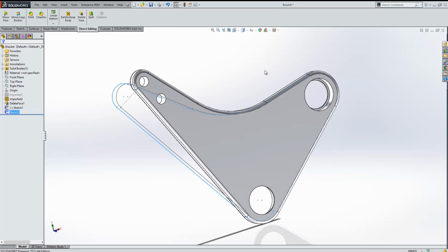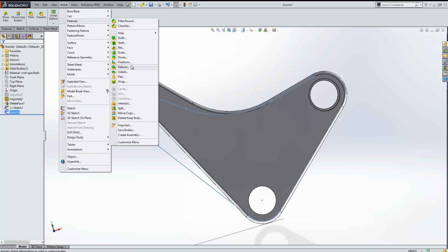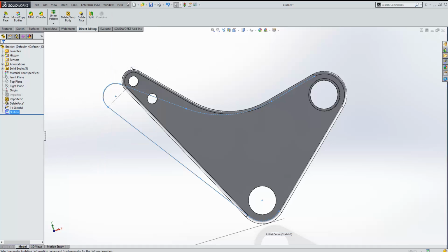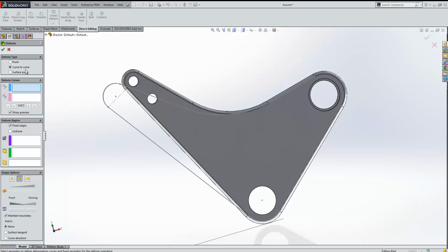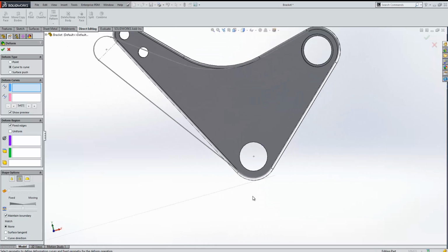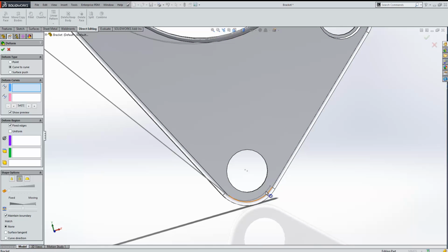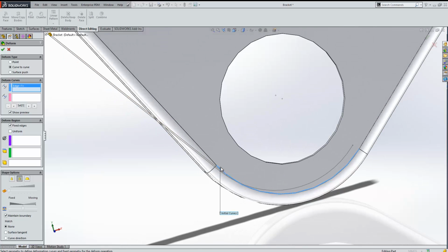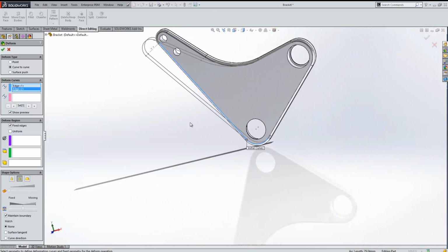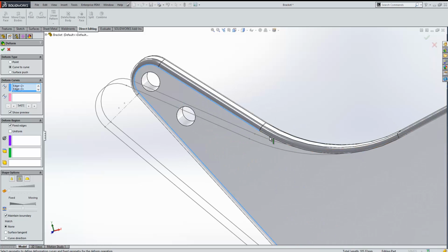And we'll choose exit sketch. And then what we're going to use is the deform feature, and we're going to use the curve to curve. So we're essentially going to take the outside curve and shift it to the far side. So which curves are we going to be affecting? We're going to be taking the original one. Now it does actually matter which selection set is in which box, because it's the curve you're moving from to the curve you're moving to.